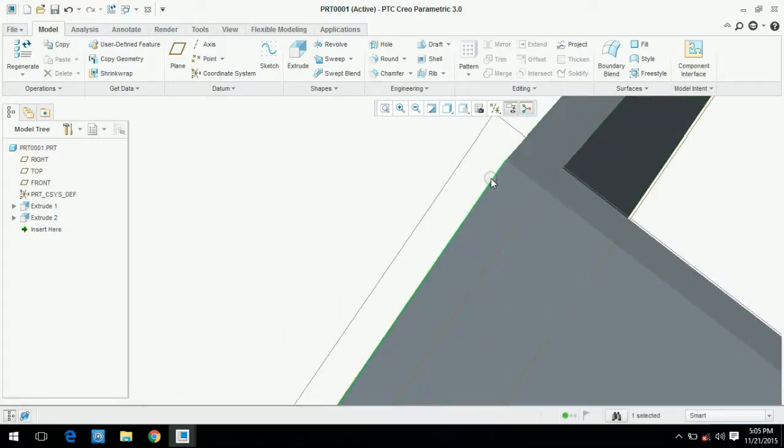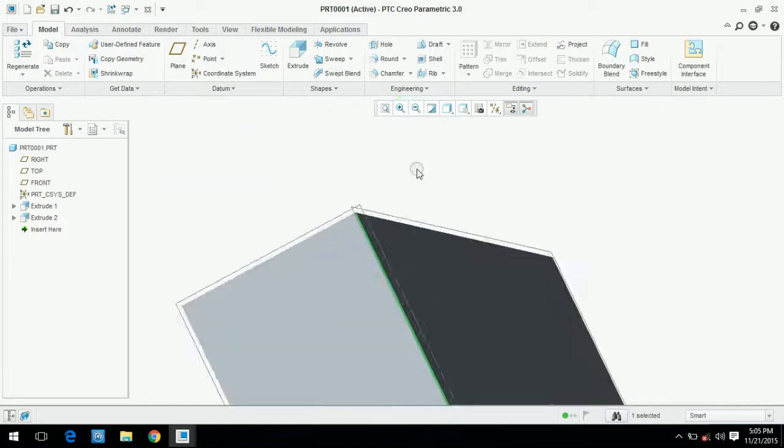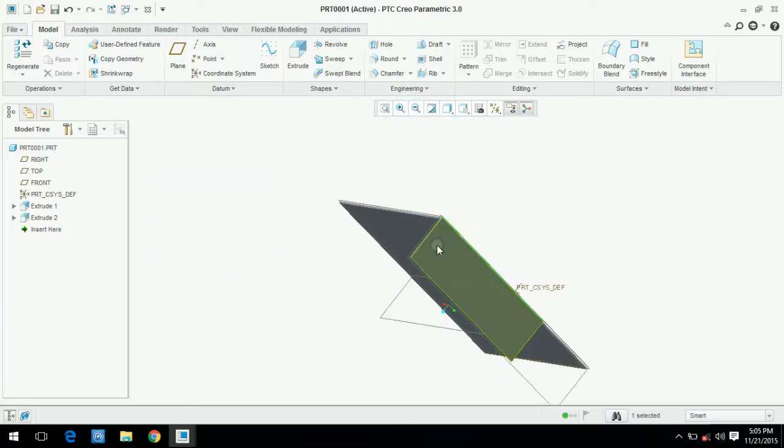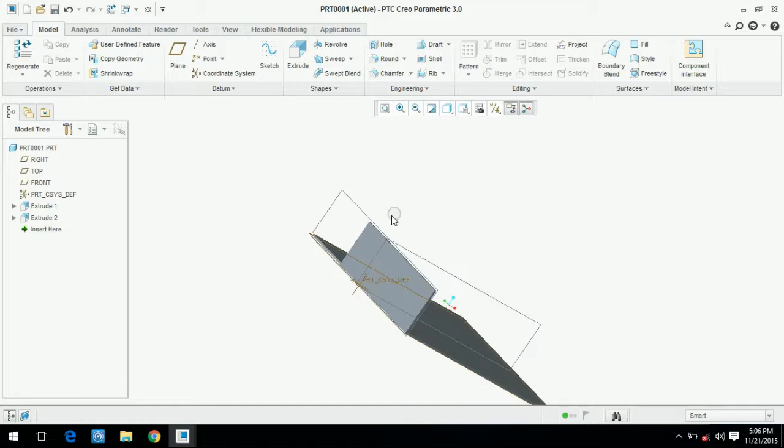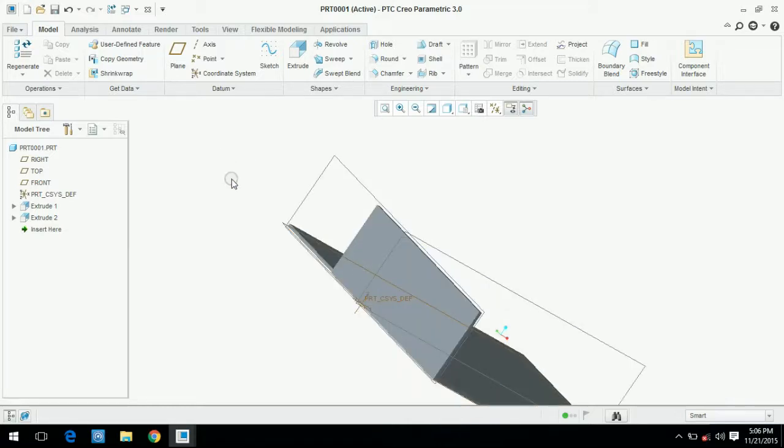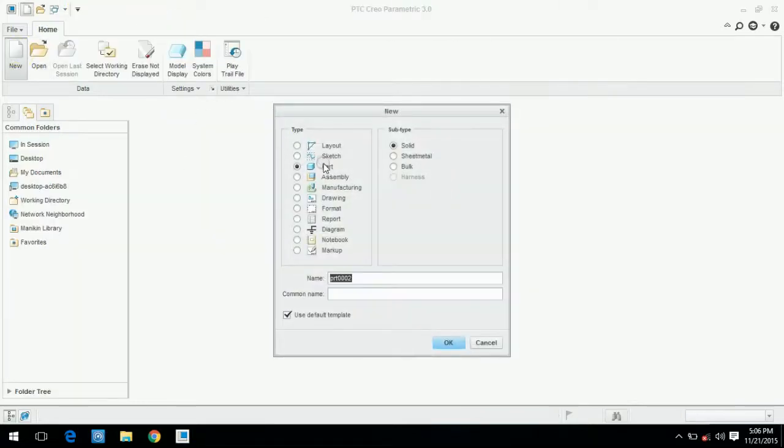but in the case of sheet metal there is no corner. Whenever we try to bend a sheet into multiple side walls or any other shapes, then in sheet metal they form a curve shape, a radius, not a corner. And in order to design a sheet metal, we will have to keep in mind several things like corner relief, bend reliefs, and etc. To overcome that, there is a special module in Creo Parametric besides the part module: sheet metal.